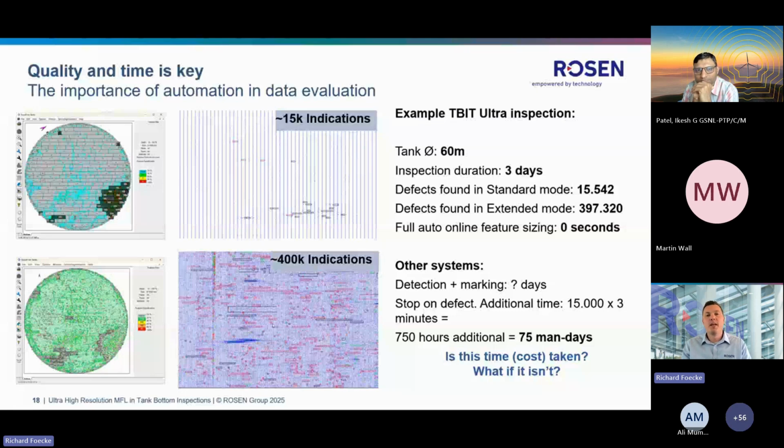And there we had a sensor spacing of around 7 millimeter between two adjacent sensors. And with the ultra high resolution, we get to a sensor spacing of 1.6 millimeter. So we are able to detect many more smaller indications, but also deeper ones, smaller in diameter, I mean. And of course, with the implementation of the ultra high resolution, we also look meanwhile at other directions. So we have 3-dimensional Hall elements on the tool.